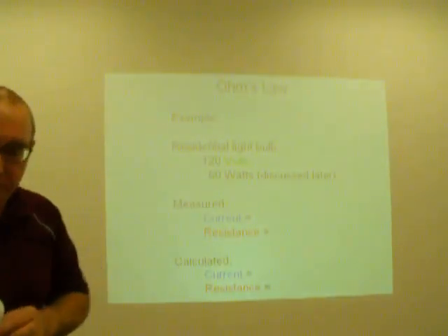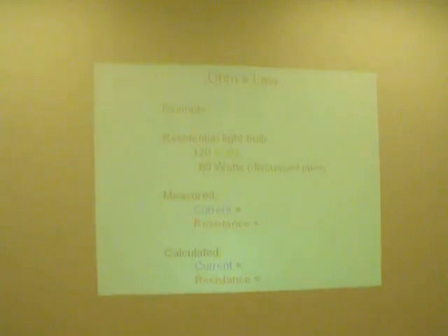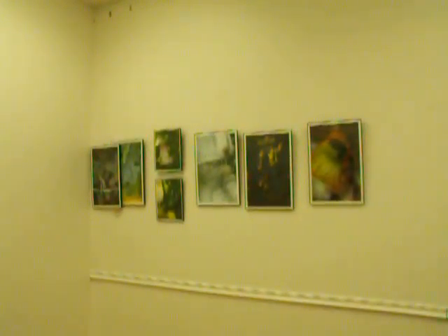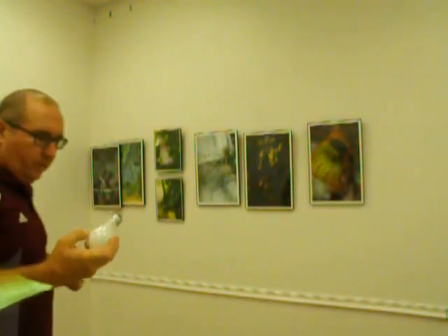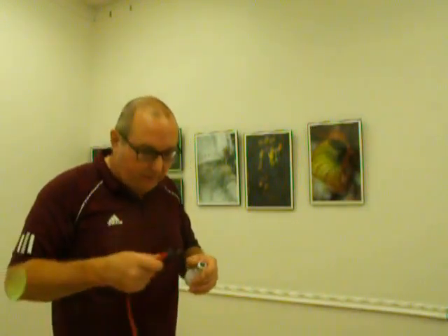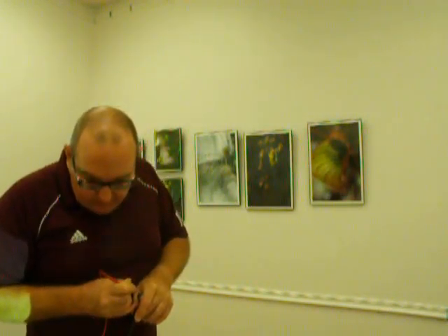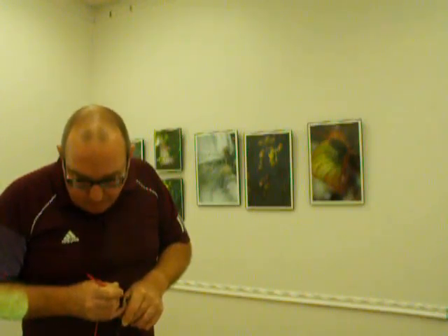So over here I have a device that I can use, a lamp holder, to demonstrate this concept. So I'm going to measure the resistance of this light bulb while it's cold. There is a significant factor here, that's why I mentioned cold versus hot or warm, as we'll see later. And I'm measuring 19.7, let's say 20 ohms.